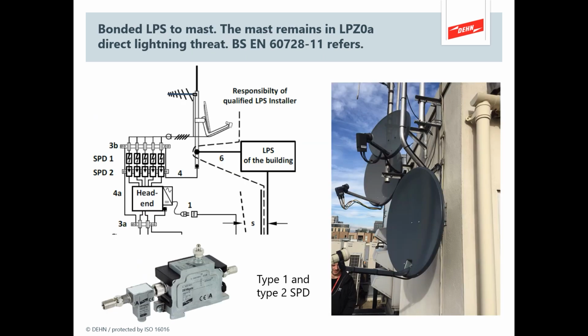In this picture, however, which is typical for installations, the copper tape, which you can just about see on that plant room, is cross-bonded to all of the bracketry and the dishes, so that is a cross-bonded system. What this means is the whole of the metalwork will be energized. What's attached to the dish?